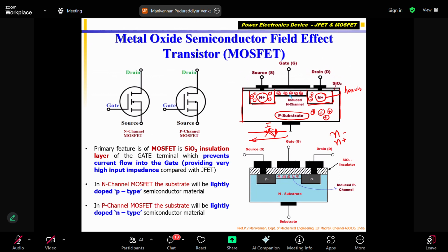So in the P-type material, you have holes and they are also randomly moving, because I added impurity aluminum in silicon. Out of 1,000 atoms of pure silicon, I removed 100 atoms, added 100 aluminum atoms. So aluminum gives positive holes. They are also randomly moving as long as you don't give external power. The holes in the P-type material, electrons in the N-type material move randomly. So there's no current flow. Only when I give external power, they force the electrons to move in one direction.